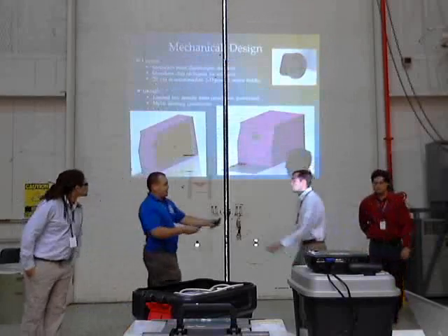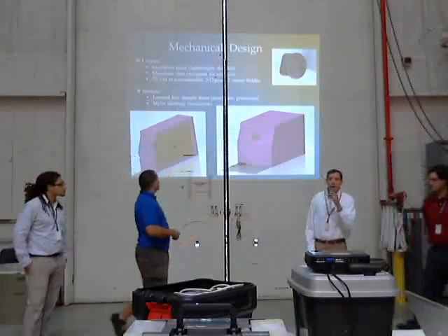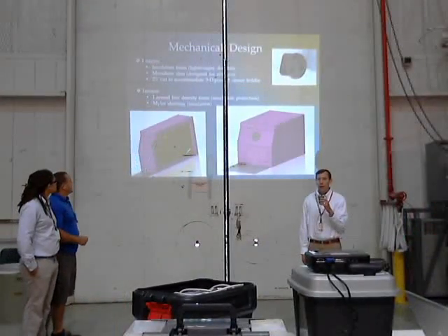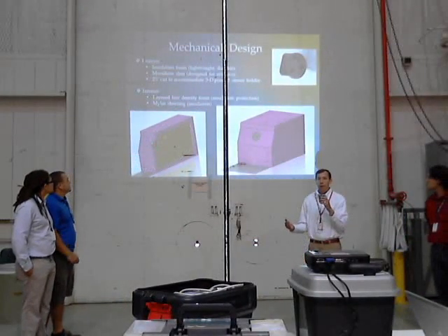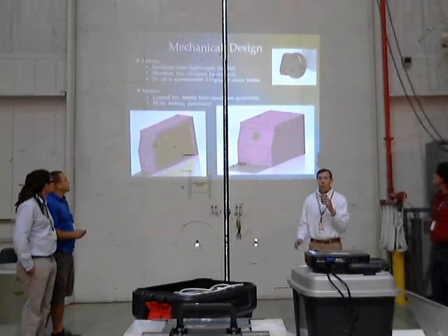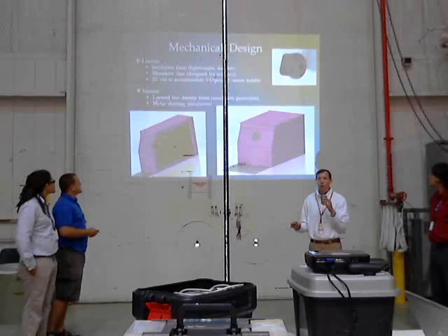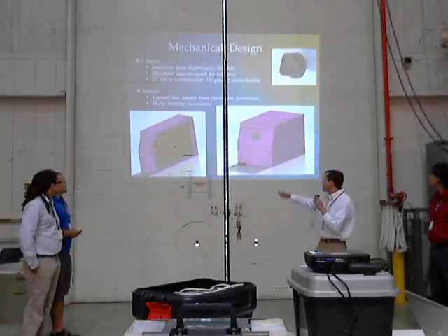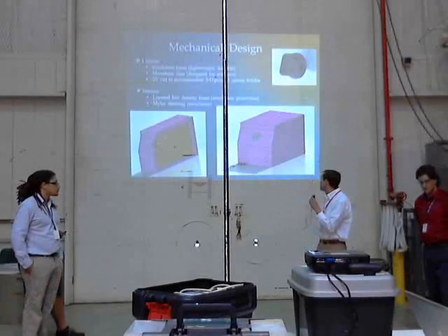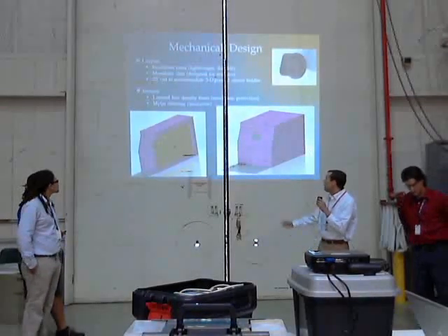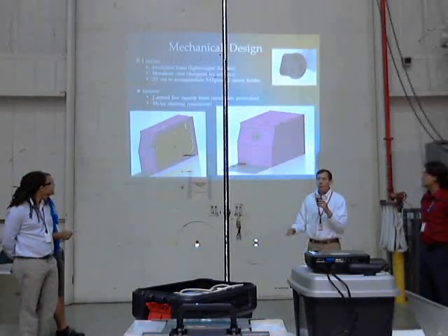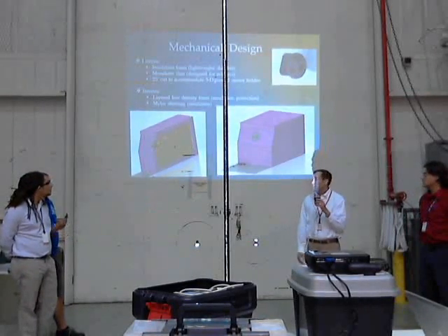For mechanical design, it's made from insulation foam, 3/4 inch thickness. That's our exterior. We also created a 3D printed lens holder. We went through a few different examples on that one. We cut the side of it in order to angle it at the optimum angle for the sun, and our interior is layered with low density foam wrapped in Mylar insulation.